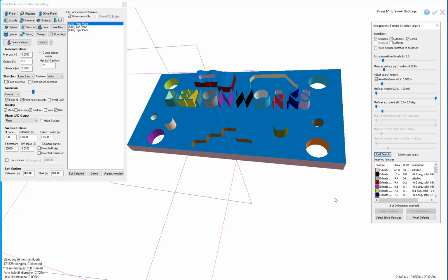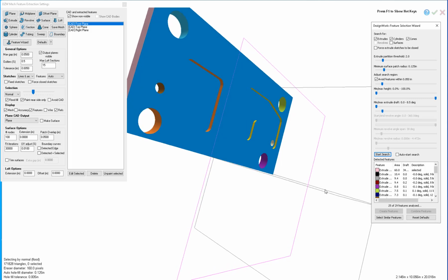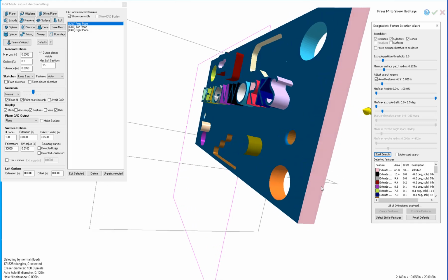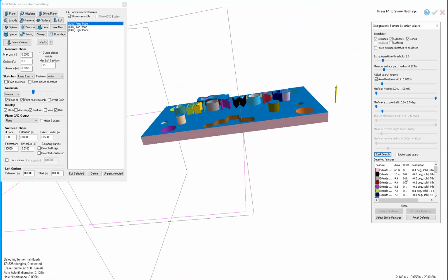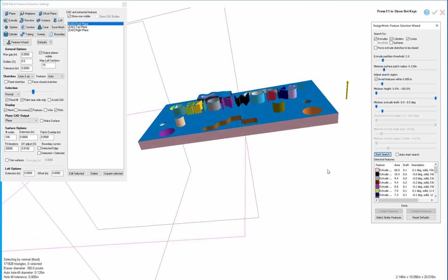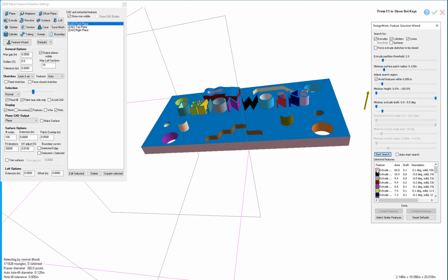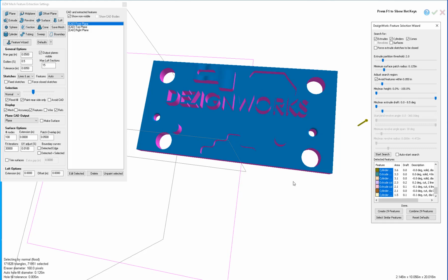A lot of guys like control, but on parts similar to this, you can run full auto. What I mean by that is let the software decide what it wants to pick. There's an AI in here that will actually reorder it. So you'll see, if we take a look at this, these really aren't in any certain order. It's just finding them. But we can go ahead and say, hey, pick this extrude. Just like Windows, you're going to hold down the Shift key and find all the features. So there it said, hey, there's all my features I want to run.